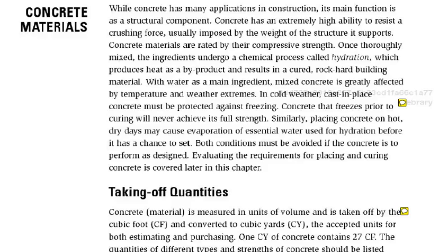It's not good for your crew. It's very hard work. A concrete finishing crew working in the hot sun on their knees, and production goes down. And there's also always a temptation to water the concrete down to help them finish it when it's real hot, which again makes a problem. You'll get spalling later on. So both for the concrete and for the people who are doing the work, extremes in weather are bad, and you want to consider that, especially when you're scheduling a project.